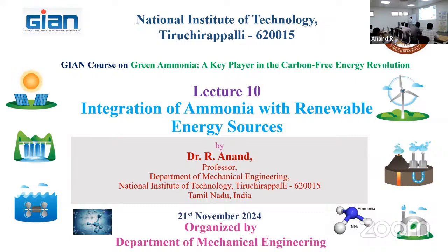We are going to reduce the pressure. Assume that here pressure is 1, pressure is 2. So we are going to drop down the pressure from P1 to P2. By doing so, the volume increases, pressure drops down, work is coming out. As you now know, work is nothing but specific volume times delta P. How much the specific volume of the fluid entering, how much the drop in pressure. So if the delta P is more, we will get more power from the turbine. That power is converted into electricity by connecting a suitable alternator.